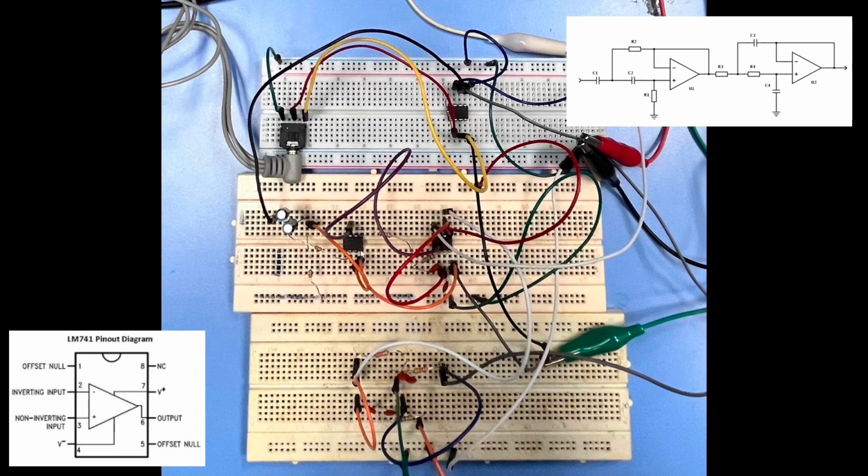The output in high pass filter will connect with the low pass input. So pin 6 here is output. The resistor will connect to pin 6 at high pass filter, and then it will connect to another resistor, and then the other resistor will connect to pin 3 in the low pass filter.